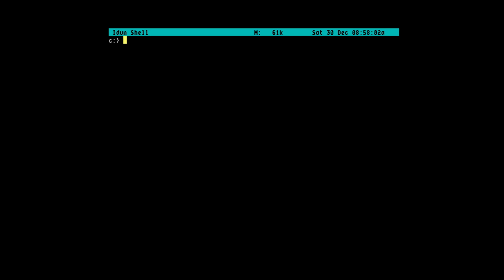So then mode 4 is our higher resolution version of mode 3. And we can do mode debug VDC 4. And you'll see you get the same color bar display like we showed before, but this time 640 by 480 resolution. So actually 4 times the number of pixels as mode 3 and 4 times the number of color cells. Practical uses for this mode, kind of not yet determined. Obviously you could do something like those ZX Spectrum images, but at 4 times the resolution, so that might be neat. But other uses are there to be explored for mode 4.